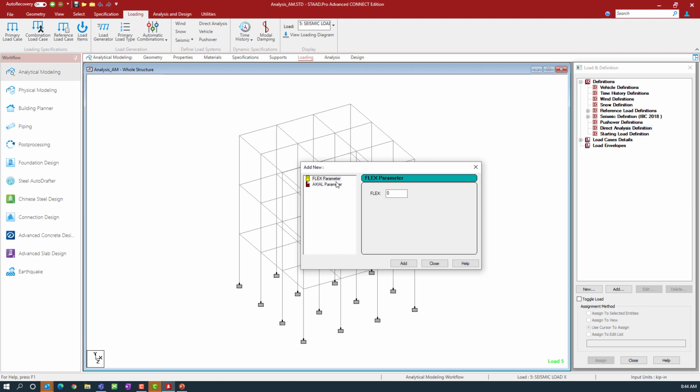Let's get started with the flex parameter. Now what gets entered into this field here? What I'm going to enter is the initial value of that tau beta factor. For more information on how tau is calculated, I would encourage you to refer to some of the relevant equations in the AISC 360 Chapter C. For this particular model, I'm going to assume an initial tau factor of 1.0. And I'm also going to ask the program to perform an iterative solution to calculate tau while performing the global solution. We're going to instruct the program to perform that iteration when we specify our analysis command.